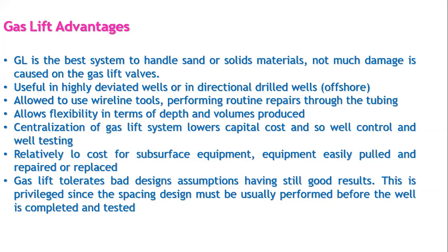Yesterday in the ESP system, we mentioned that one of the problems with ESPs is that any sand or solids production will be catastrophic for the ESP. In this case, we are not having any problem. We are not having any pump or something like that, so we are able to produce sand or solids.